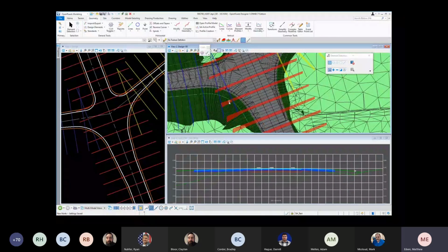Okay, so when we hover over a name boundary with our cursor, we'll see a little prompt come up that tells us which boundary we're on, which level it's on, and such. So I want to go ahead and do station 125. When I select on this, I'm going to get the handles or grips that MicroStation has for the elements. When I hover over one of these grips, it's telling me which number it is.